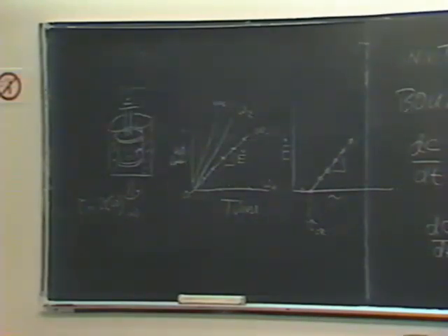is that it's not just the waste discharges, it's also the fact that the freshwater outflow has been reduced to the point where the mixing zone now has moved way up into the system, and there's much less ocean water diluting it. So the residence time has increased. That is, the time that the water stays in a region has increased a lot. And if you have continuing waste discharge into that, it means that the ambient concentration gets higher. So the problem is a combination of less freshwater outflow and increased waste discharges.